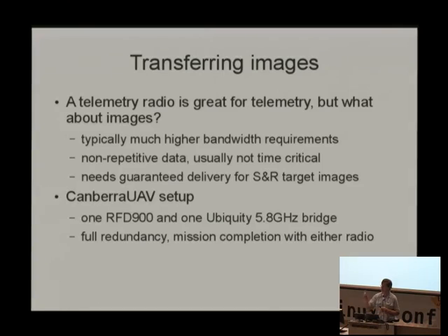That meant we had to get all our images over this 57600 serial link. Now, images across a 57600 serial link, the raw images from the camera are 20 megabytes a second. So we need a lot of compression. And we still want all our telemetry and command and control to go as well. We had a budget of around 2 kilobytes per second available for sending images across this radio link.